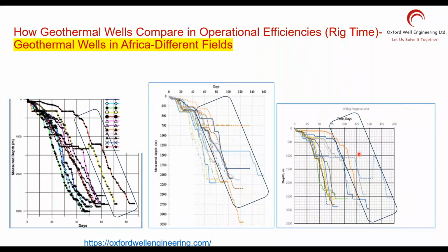And look on the right-hand side, massive sidetracks, a lot of sidetracks, maybe two in one, two sidetracks, one sidetracks. All these humps are sidetracks. It's not optional. They run into problem. They could not come out of it. They bury the BHA and drilled again. So these are the things that is all around the world.